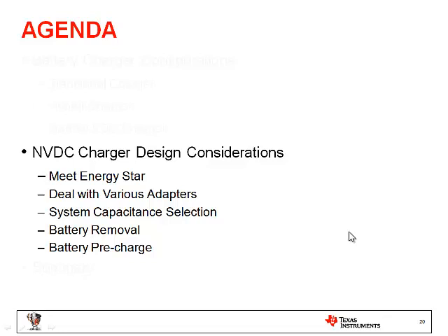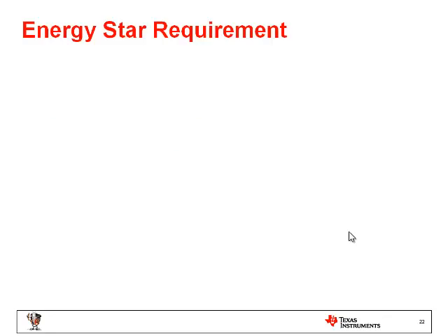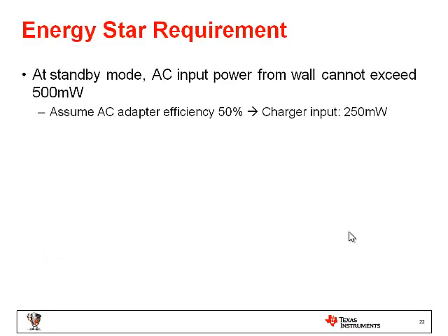Let's talk about NVDC charger design considerations. First requirement is Energy Star. Energy Star means total power draw from the wall when the computing device or mobile device is in a standby state. So here is a diagram about how we define this total power from the wall.